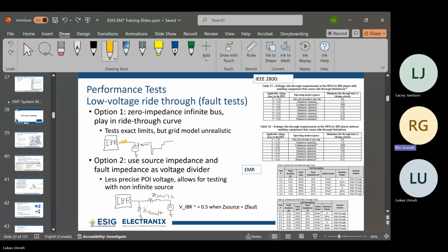In 2800, if you're testing voltage, you're looking at voltage. Testing reactive power, you're only looking at reactive power, and that's where the requirements are. There are other requirements like ERCOT, where for voltage ride-through, you need to maintain active power at the pre-fault level plus reactive power magnitude, which is, I guess, maybe two different control systems at the same time. It's definitely a capability thing.